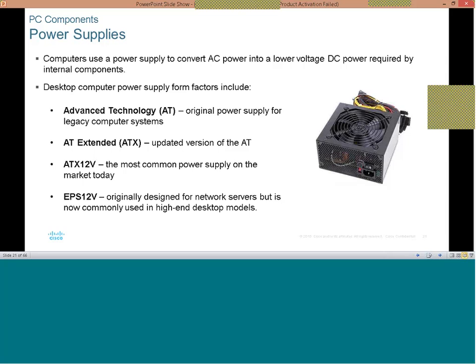If in your area you use 220 volts, you're meant to preset it to 220, and if you're using 110 volts, you maintain it at 110 volts. We've had cases where technicians have messed up systems because they didn't take proper precaution in checking the power switch. You need to check it and adjust it to suit the power system in your country.